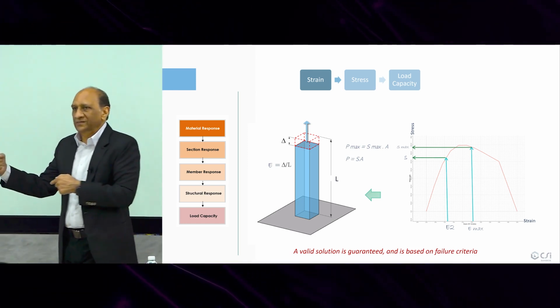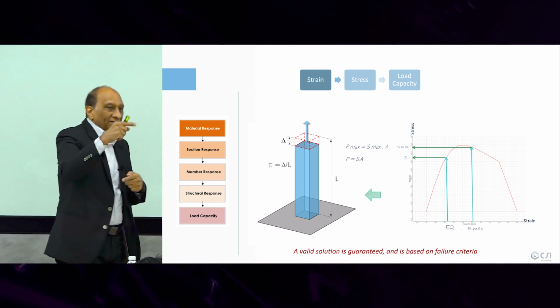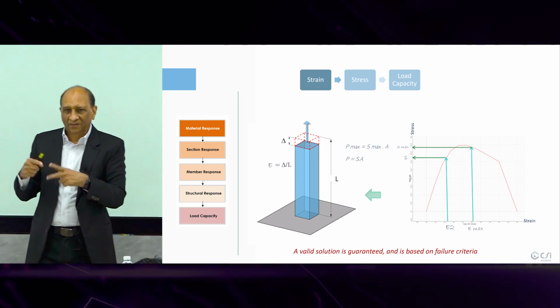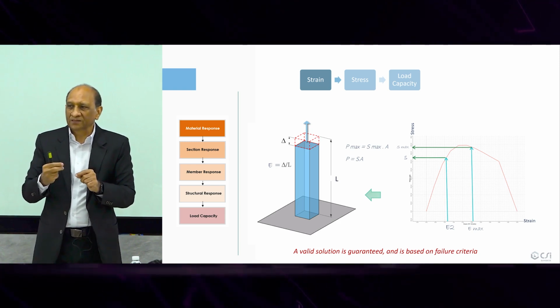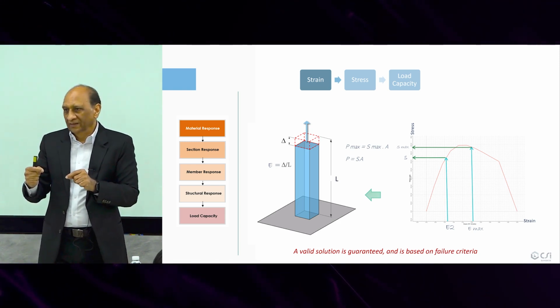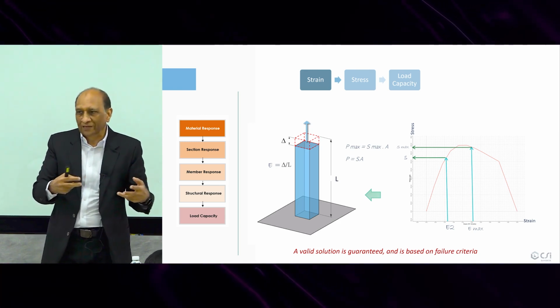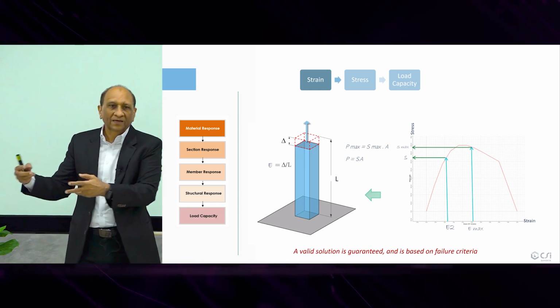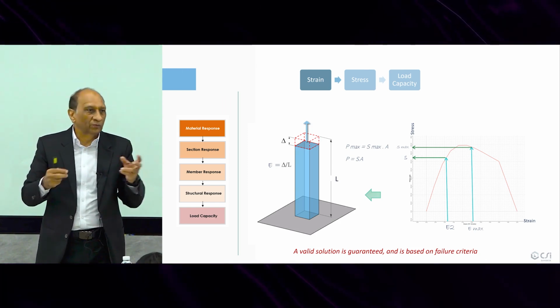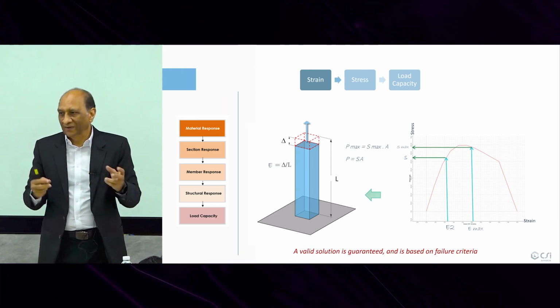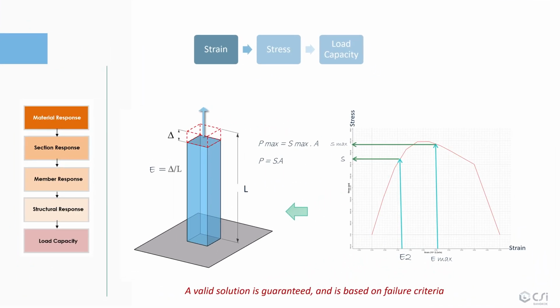And then we can check that load capacity against applied load to calculate the real factor of safety that is available. It's like a summary of the pushover analysis, kind of, right? Because you calculate the real capacity, true capacity based on the material. So now if you have a particular structure to evaluate, you start with the material, testing material numbers, actual cross-section, actual thing, you can calculate the capacity very reliably, and then you can compare it with whatever loading that you want to compare and see if it's valid or not valid. So this reverse direction works very well, and that becomes the basis of all of our further development. All right, so then we get the P from there.